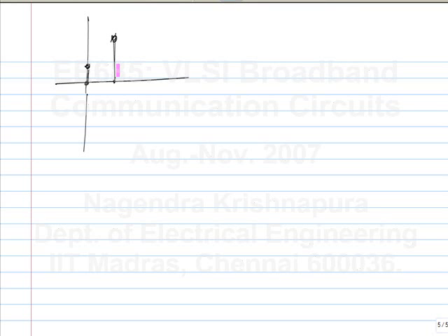You need to have coefficients larger than 1, but what is the problem with that? That is some implementation detail. We can do that. No, we are talking about DFE. Okay. So, this one I can't make a DFE if I think of this as the cursor. But I can make a DFE if I do think of this as the cursor. Then I make the decision and subtract something, and that ratio that happens to be more than 1, that's all. Okay. That's not a problem at all.